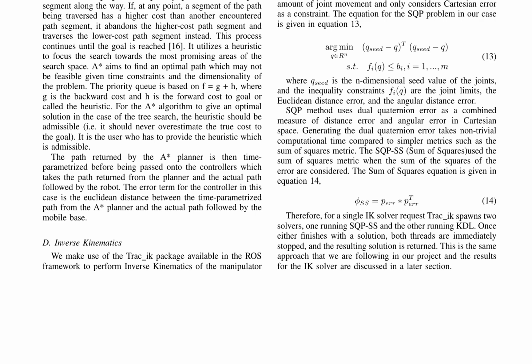For the mobile base, trajectory planning is performed using the A* path planning algorithm. The algorithm is first tested on a PR2 robot in the OpenRAVE simulation environment, generating paths for 4-connected and 8-connected spaces using Manhattan and Euclidean heuristics. The results demonstrate the superiority of the 8-connected Euclidean heuristic, with a lower cost and fewer nodes explored. The path generated by the A* planning algorithm for an 8-connected space with Euclidean distance heuristic is shown in Figure 9.